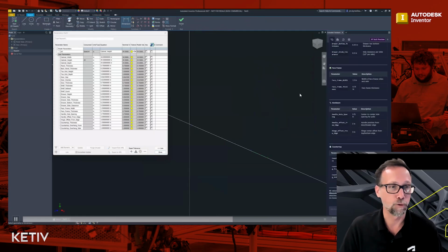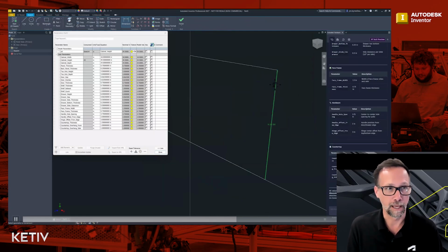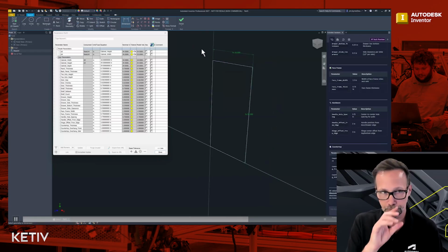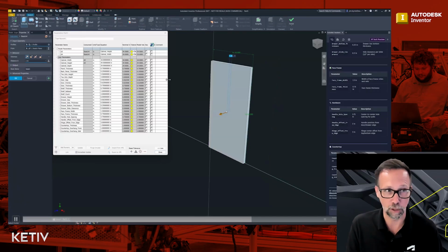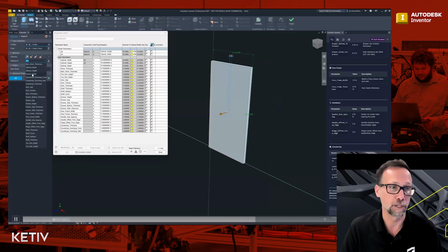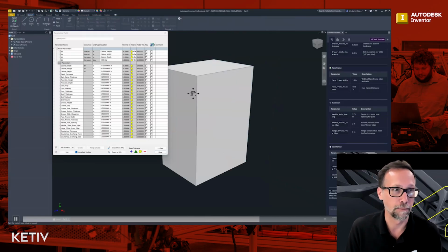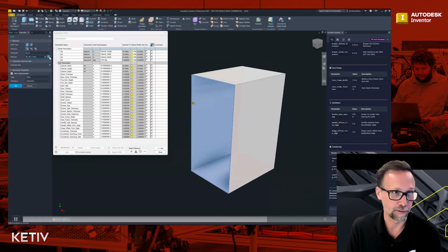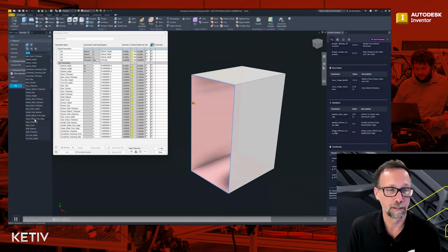And then if you haven't used parameters, once you've created those and you begin modeling your part, or maybe you've already modeled it, then you can attach those parameters to those dimensions or maybe a feature dimension. In this case, like a shell feature, we can pick that parameter from here.